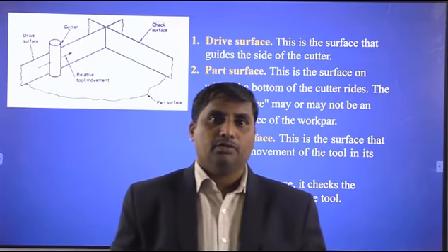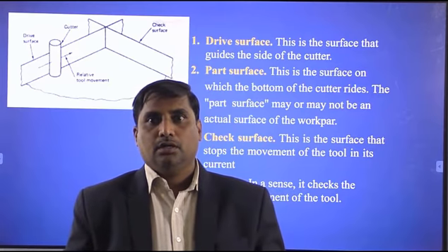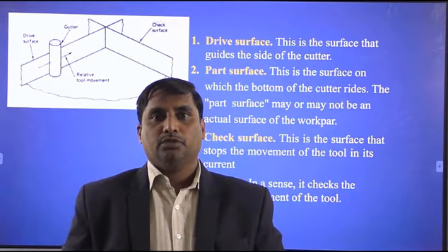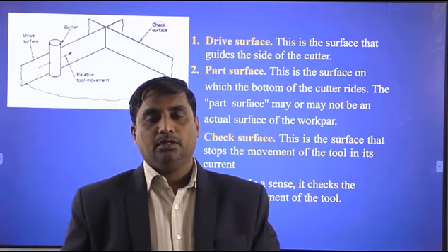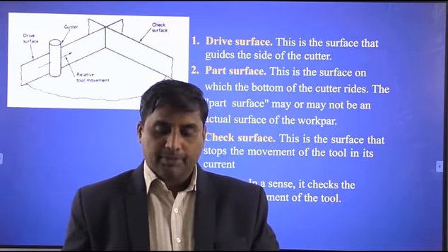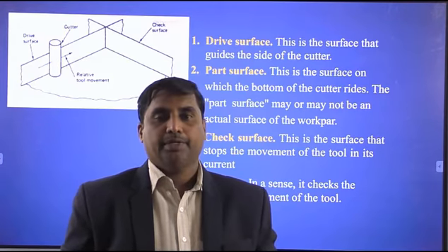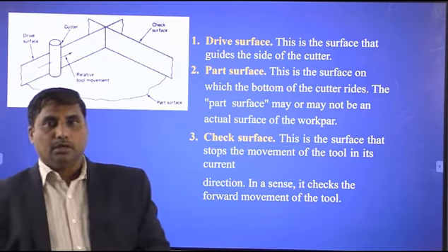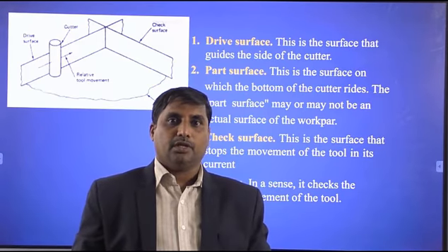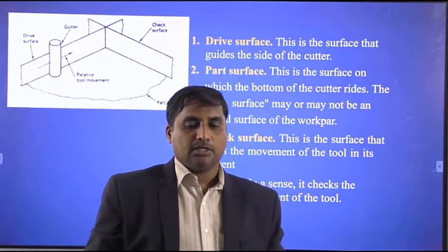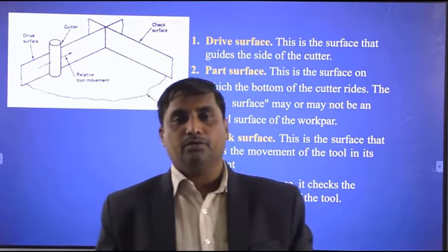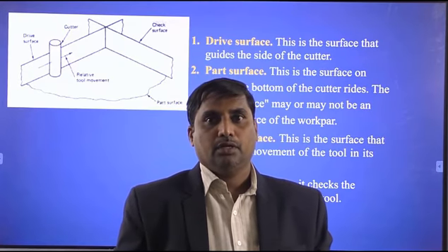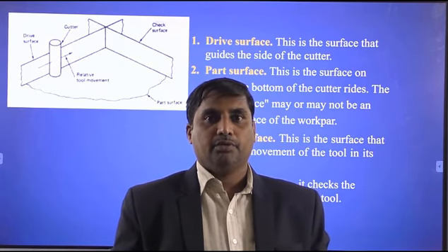In the previous lecture, we learned about the rapid motion statements and geometric statements. Regarding motion statements, I explained the rapid traversal and incremental movement of the cutting tool by taking two examples. Next is generating contour shapes, that means irregular shapes. In that case, we have to continuously guide the cutting tool to get the required shape of the work part.